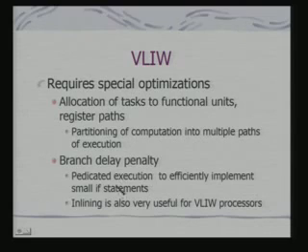Similarly, for VLIW processors, the scheduling of instructions as such need not be changed because of this problem. So, what we say is use predicated execution to efficiently implement small if statements. I should use conditional instructions to implement a small if. I should not make a conditional jump. The moment I make a conditional jump, the entire set of instructions to be executed has to be changed, and that introduces overhead, that introduces branch delay penalty, which should be avoided.